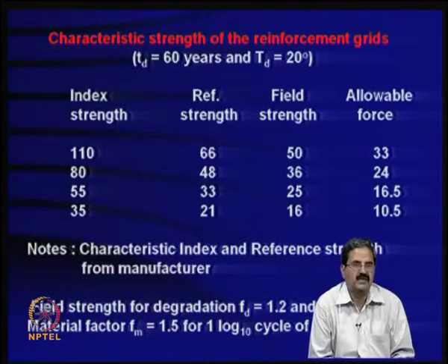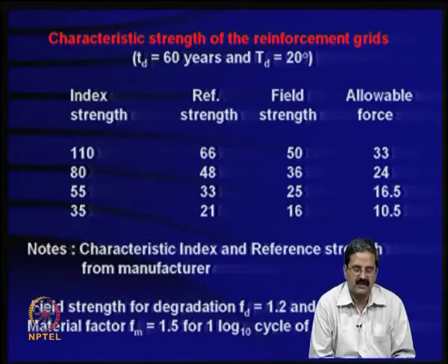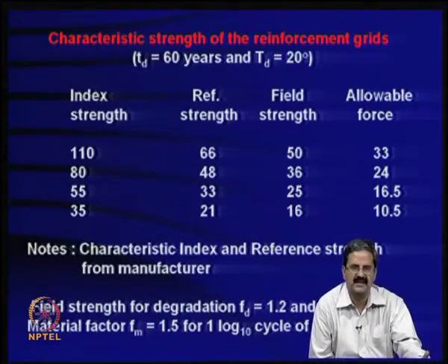In fact, as just mentioned, the tensile strength reduces with time. I showed you the diagram. If you test for 1 hour, there is a test where you test immediately and test for a few, like 10,000 hours, at least up to 42 days also. People can continue the test, take the samples, measure the test, get the values, and one should understand that, and then they extrapolate.